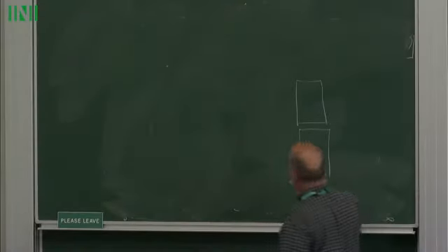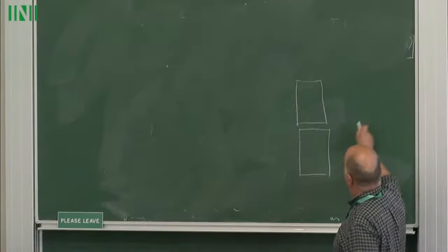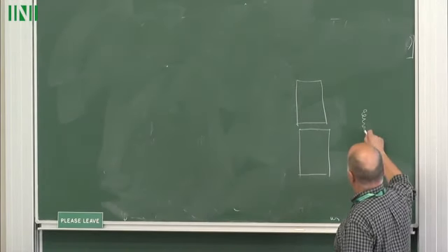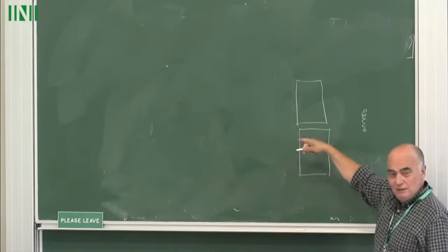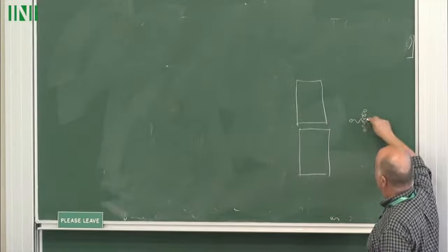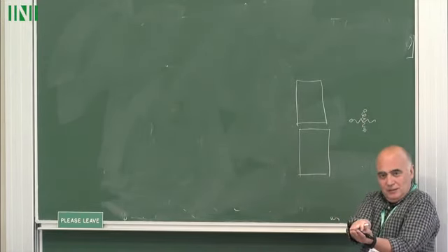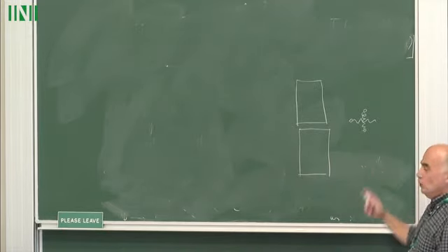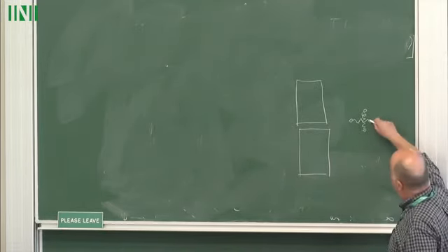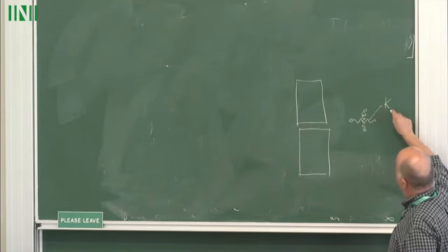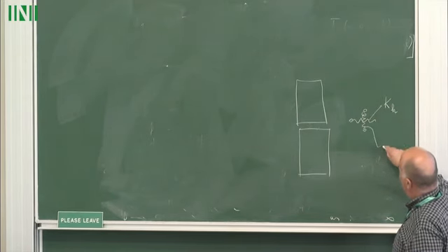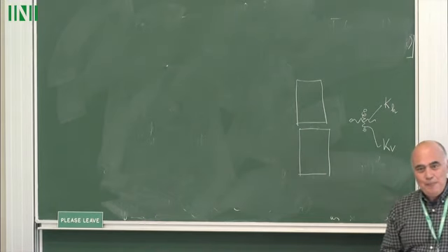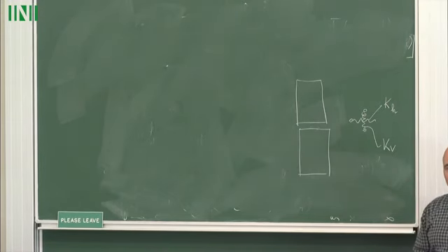Elastic, yes. And we have put inside here a spring interface, both longitudinal and tangential. So a spring interface in this direction and in the shear direction. Now, imagine this stiffness is K horizontal and this stiffness is K vertical. If you make KV too large compared with the KH, you obtain this.